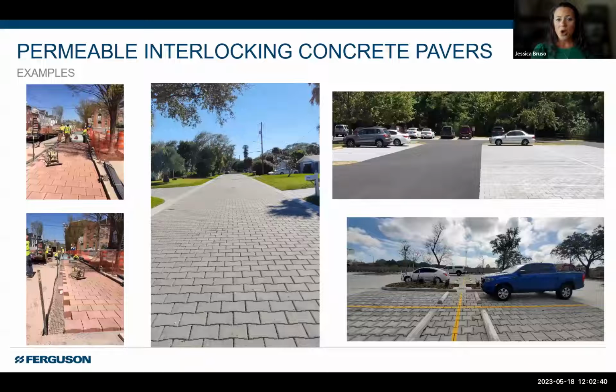We do have, again, parking areas, and both of these parking areas that are on the right-hand side, you can see we kind of have that run-on condition. So keeping those drive lanes in asphalt, directing the water, making sure it's graded so the water's directed toward those spaces, and using them like inlets.